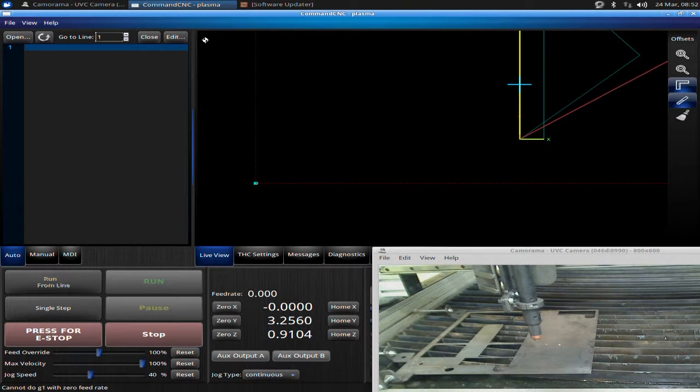And then you know that there's nothing on there that's going to cause a problem. You leave something on the rails, a wrench or something like that, that gets in the way of the gantry. What it's going to do is stall the motors, and it's going to stop the gantry from moving. And what happens is the machine will think the motors have moved, whereas the motors haven't. And so the machine thinks it's in a different position than it actually is.